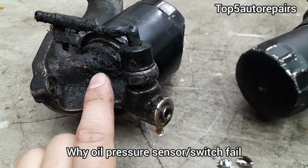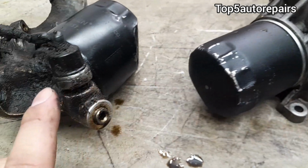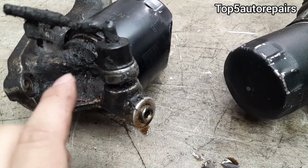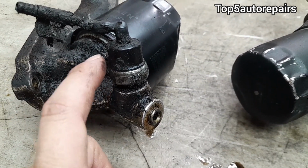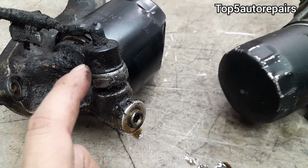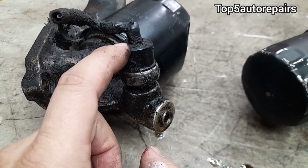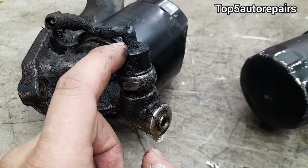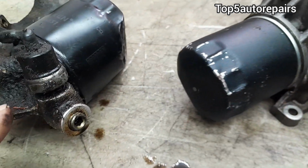The number one reason why this oil pressure sensor switch or sensor fails is going to be caused by an engine oil leak. If engine oil starts to accumulate directly on the oil pressure sensor switch or sensor, it's going to cause a connection issue. This can cause a malfunction code, a circuit code, or even a voltage code.